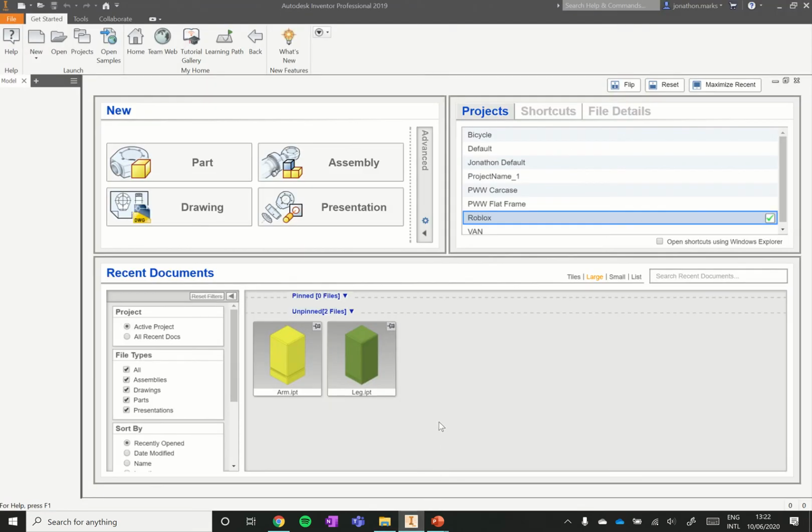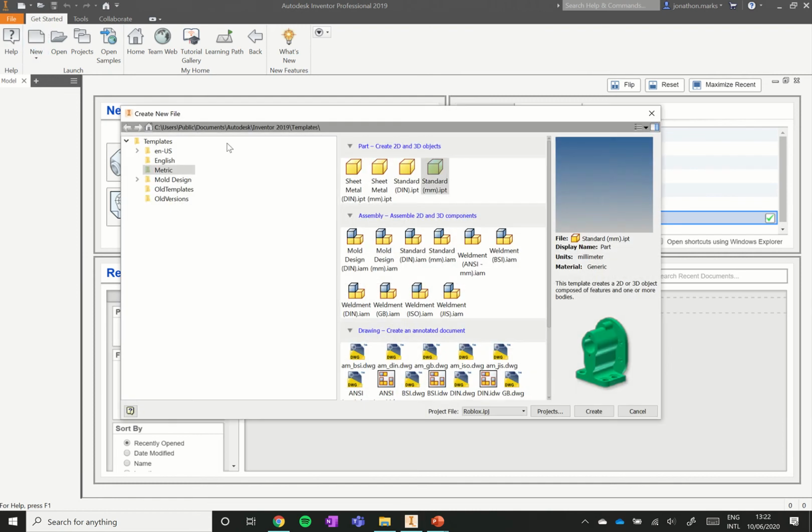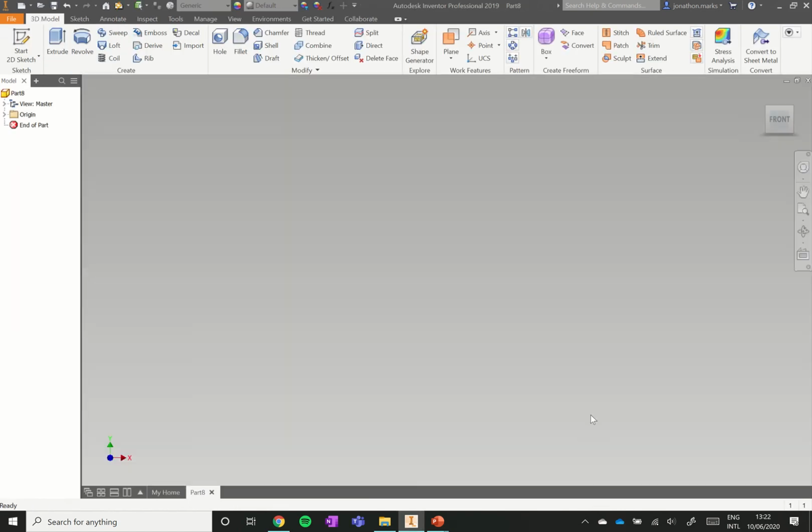And I've already got it opened up. Remember, you can find that under the Start menu under the folder for Autodesk. It's Autodesk Inventor Professional. You might see your previous files here, but you'll need to go up to New to get started in this tutorial and click the page icon. Just as before, we're going metric, clicking on that, standard and then clicking Create. And it's the same environment we've been in before.